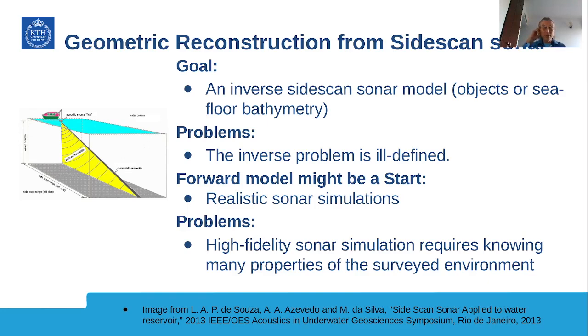So we want to invert that, and that inverted problem is, of course, a little ill-defined, because, as you probably know, the sidescan is giving us these ranges away from the vehicle, but it's this entire wedge that you get an intensity from. So you can imagine intensity at each of these arcs here. It's basically accumulated signal along this arc. Most of the arc is the water column, and there's not much reflection from it. And then this point along the bottom is the most of the reflection. And the problem is we don't know where along this arc the reflection came from.